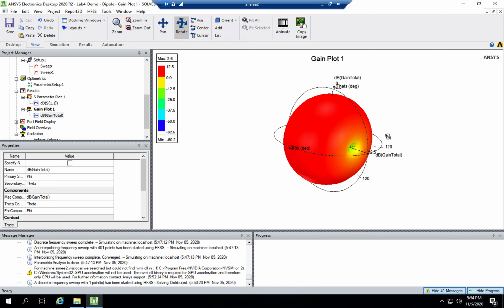All right, so the next part is to plot the copolarized and cross-polarized gains at the design frequency in two principal cuts. All right, so you guys can see that this power distribution that you see for the 3D case, it's descriptive, but it doesn't really tell us everything we need to know. So here I plotted the total gain.